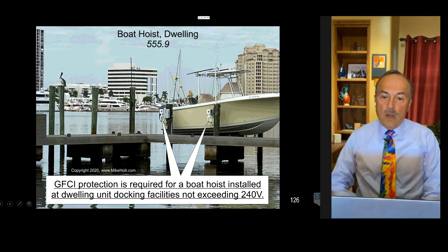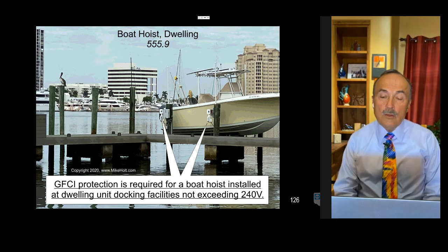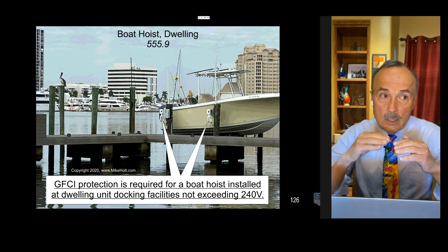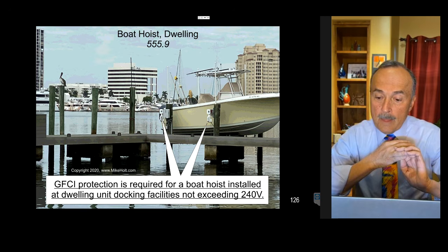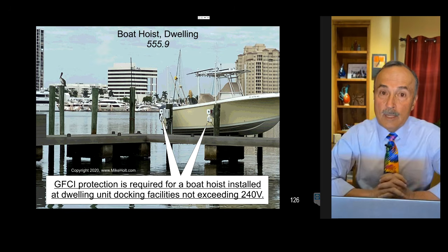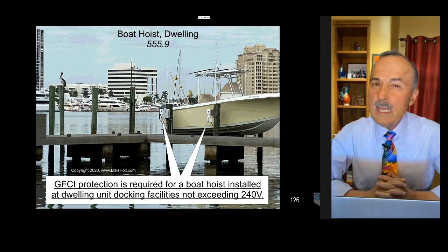GFCI protection is required for a boat lift installed at dwelling unit docking facilities not exceeding 240 volts. In other words, it doesn't matter how many amps. If it's 120, 208, or 240 volts, and it's a boat lift at a dwelling unit docking facility. What does that mean?